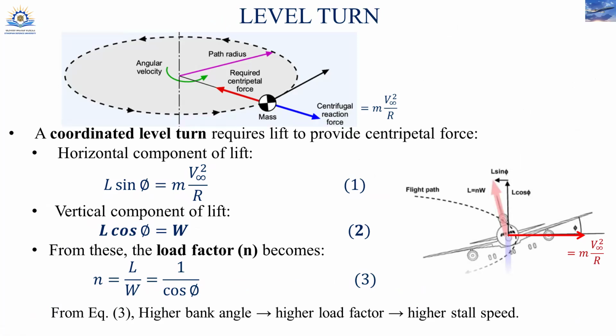That is the circle where an aircraft is circling at a given altitude. So while it is leveling there, what happened? There is a centrifugal force in the outward direction because there is centripetal acceleration toward the center, right? For that, there is centrifugal force, that is mv squared over r.